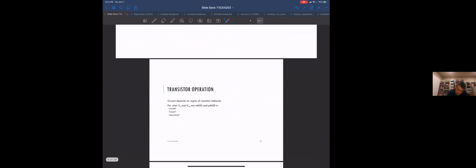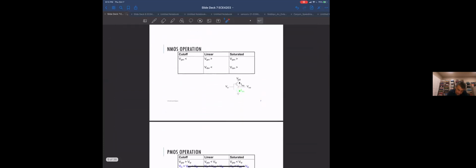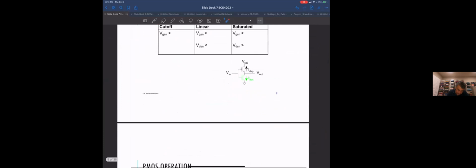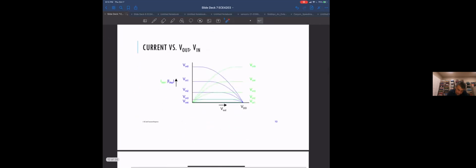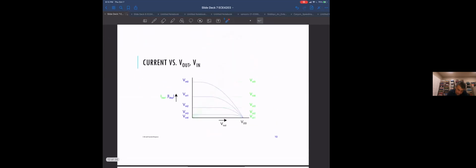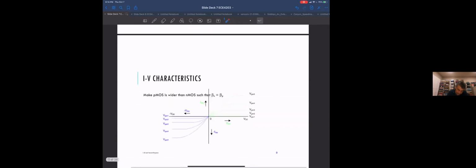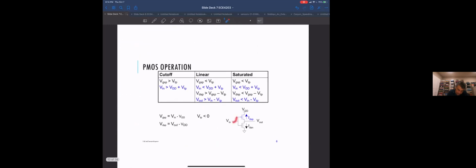As a punchline, we're going to look at the transfer function for the NMOS and superimpose the transfer function for the PMOS on the same graph, and where they intersect is the solution for each VGS, because the gates are connected together.